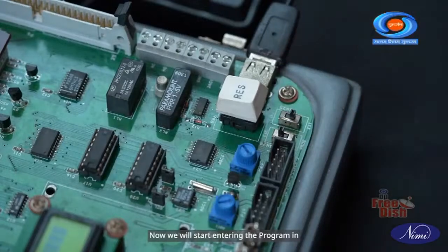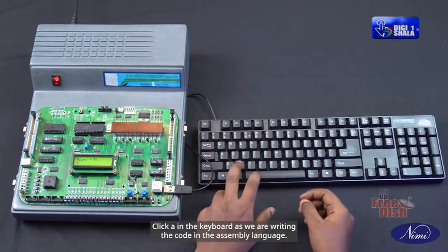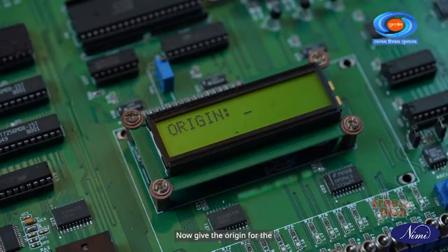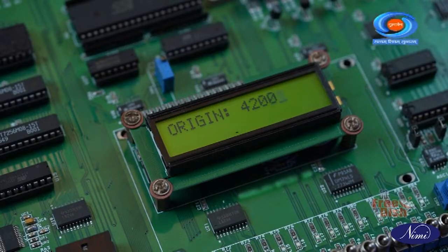Now we will start entering the program in the microcontroller kit. Click A in the keyboard as we are writing the code in the assembly language. Click Enter to proceed. Now give the origin for the microcontroller. Here we are giving it as 4200. The origin starting address will be changing from kit to kit.